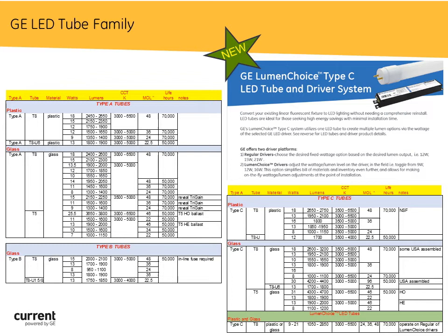And then I have tubes that are in various wattages, ranging over various lumen levels. You'll notice that our typical color temperature range is somewhere between 3,000 and 6,500. We have tubes that are both 2 foot long, 3 foot long, 4 foot long, and 8 feet long. We also have U tubes, the U 6-inch center to center and the U 1 5/8 center to center.